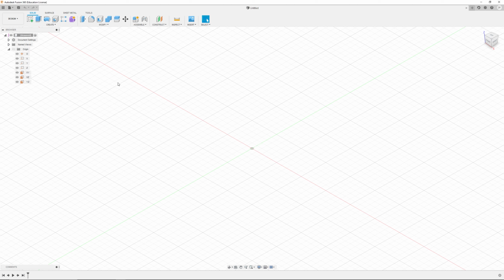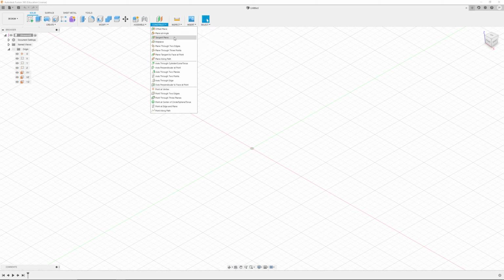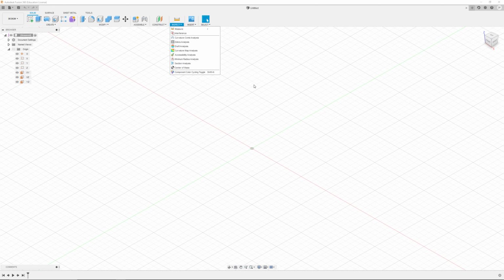And these are the bare bone structure of what makes up the initial definition of some of our geometry. And we'll talk more about these, especially when it comes to construction geometry. This allows us to create planes, axes, and points based on our geometry that we actually have created. And it's very important that you learn how to use construction geometry, because it allows you to create more additional features based on what you're working on. And if that doesn't make any sense, hopefully it will make sense later.